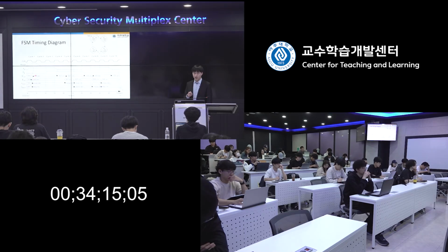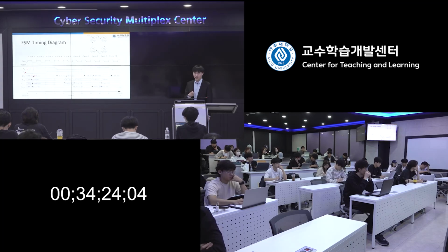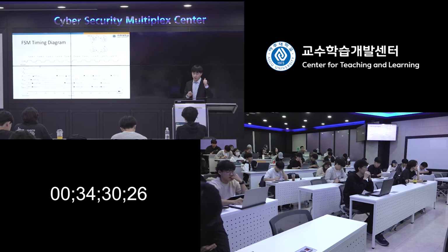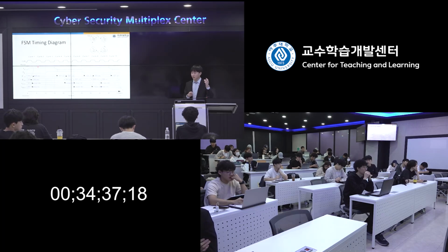Okay, so now actually S prime is the state that will be synchronized through the register. So from now on, we need to check the TA and TB. TA, TB are the sensors. If it's true, it means it has traffic. If it's false, it means that it doesn't have traffic. So TA is at this. If you look at here at this moment, it is 1, right? Means there's traffic, there's some pedestrian walking by, then we just need to maintain the current state, S0.